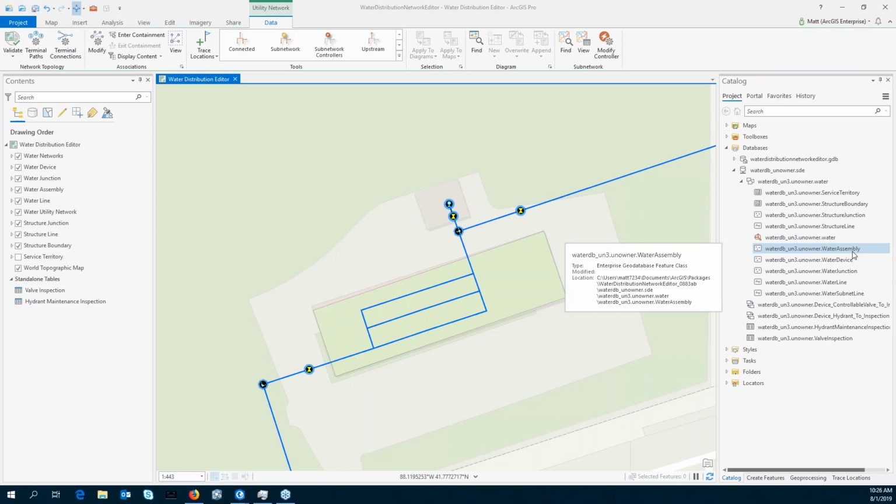You may notice that there's only 5 feature classes that make up all your domain-specific asset data, and you may think that that seems like a very few number. Now this is designed like this on purpose. Historically, you may have 20, 30, 40 different layers for your assets, but what they've done is they've parsed it down to only 5 feature classes, and this makes things run in a much more performant fashion.